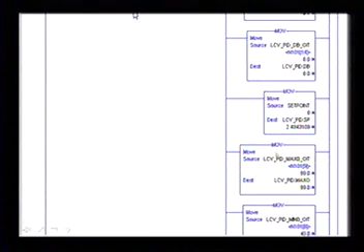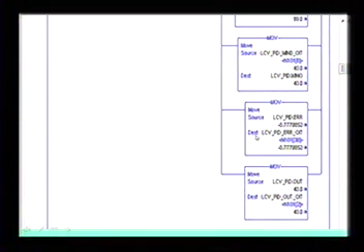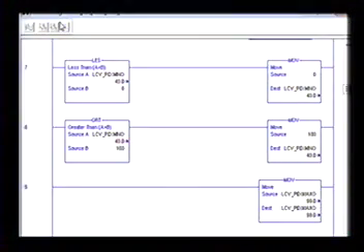Okay, so here you've got your max O and your min O. That's the maximum value the control variable can go to, and your minimum value the control variable can go to. And then you've got your error. What I'm doing here is taking the PID.ERR value and putting it in a value called LCV PID_error_OIT, and I display that on the OIT. Then I take the actual raw output the same way and throw it on the OIT as well, so that they can see their error and they can see their actual PID level control valve's output position and know what this thing's doing.